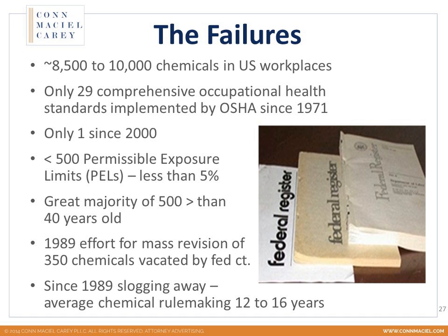Of the 500 PELs in Table Z, the large majority are more than 40 years old. They are based on ANSI or ACGIH standards that were brought over when OSHA was established, when the OSH Act passed in the early 70s. Under Section 6(a) of the Act, OSHA had 2 years to adopt national consensus standards into regulation. It engaged in rulemaking activity under 6(a), adopting nearly all of the PELs that you see in Table Z today.